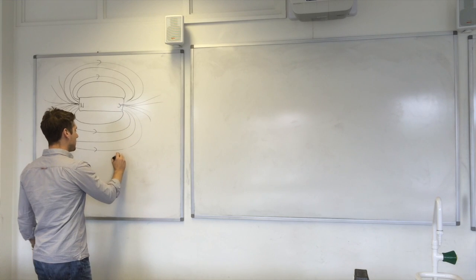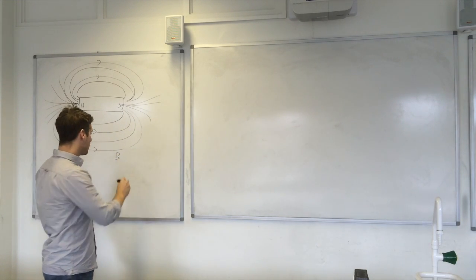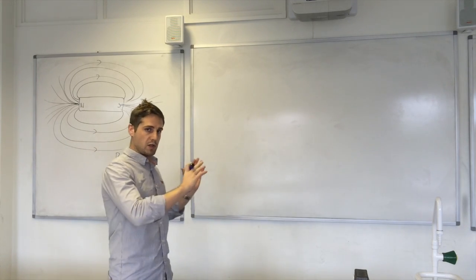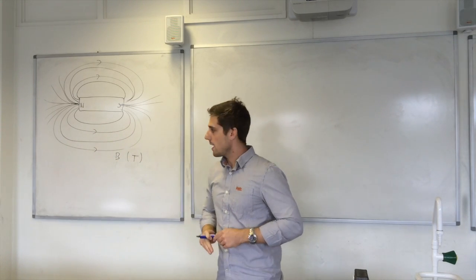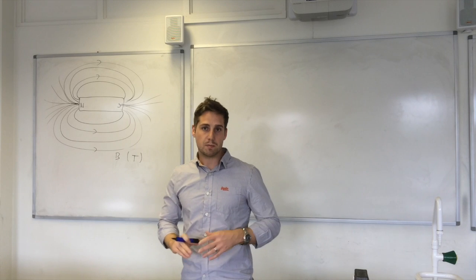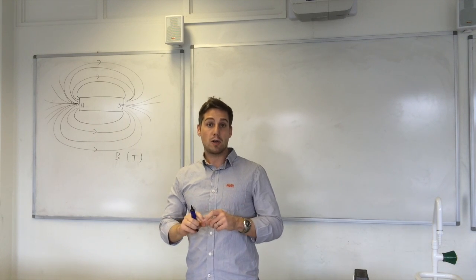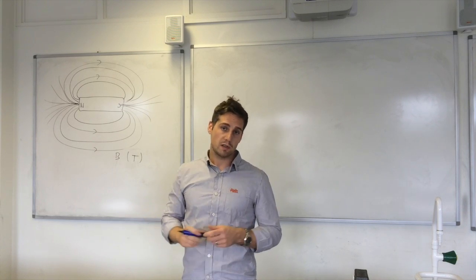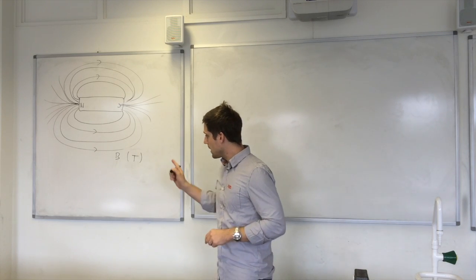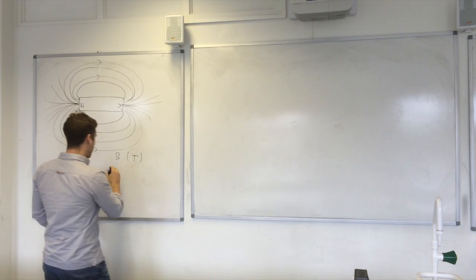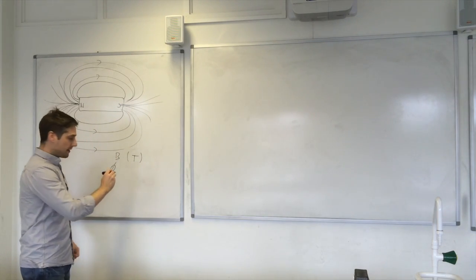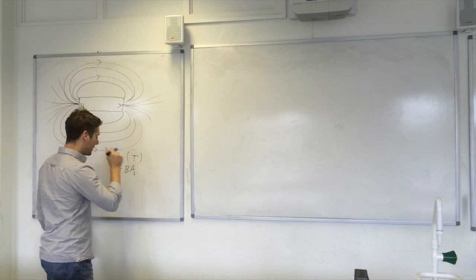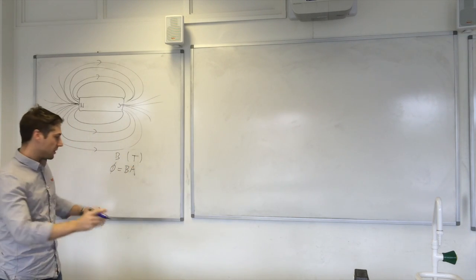And then we have some terms to measure our magnetic field as well. So we've got flux density with unit of Tesla, and that's actually defined from an equation that we'll get to in a moment. So that is the force experienced by a conductor per unit length, per unit current that it's carrying perpendicular to the magnetic field. And then we have flux, and that is equal to B times A, the area that you're actually considering.